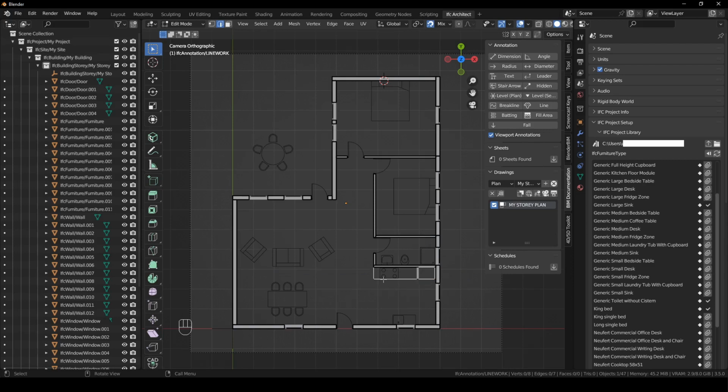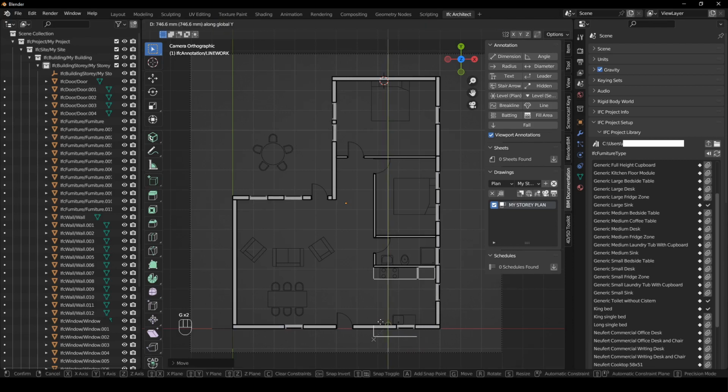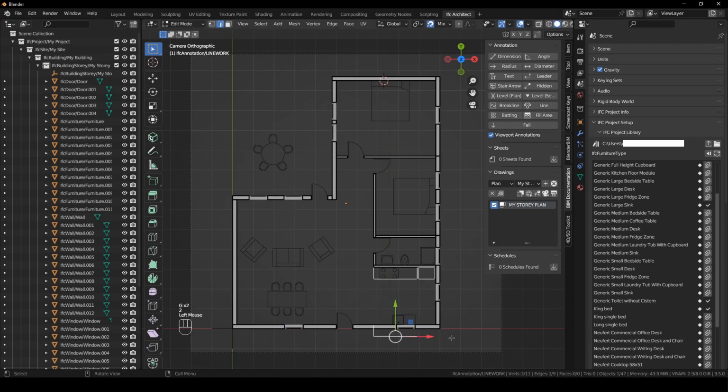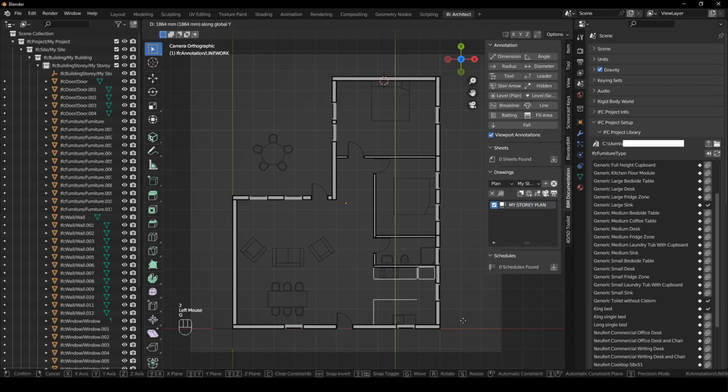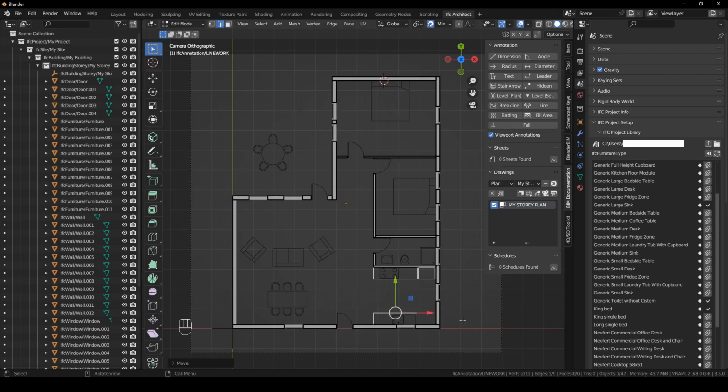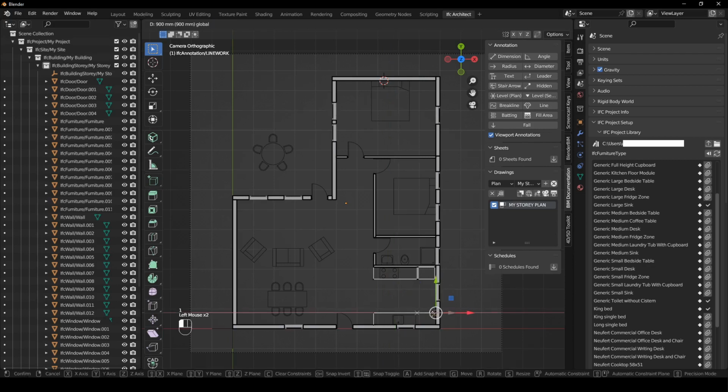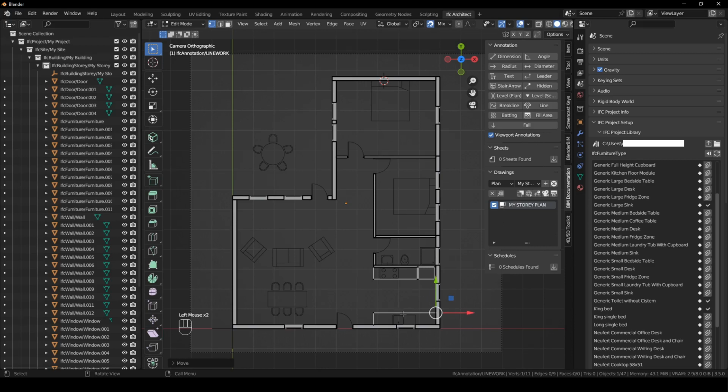Then we can select these guys as well. Select 2, select just this guy, I think, or both of these guys. Shift D and then Y, bring it down. Bring down GY so that it lines up there, and then select 2, select this guy, GY 1 to 100. Press 1, bring it across, and there we've got a countertop.